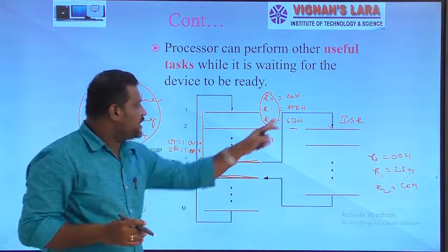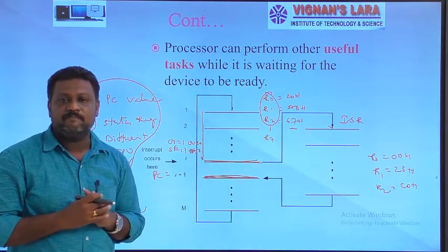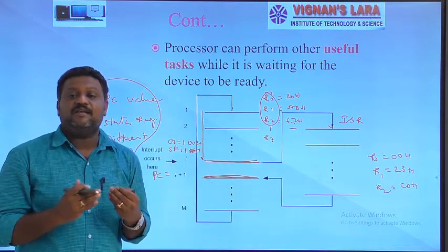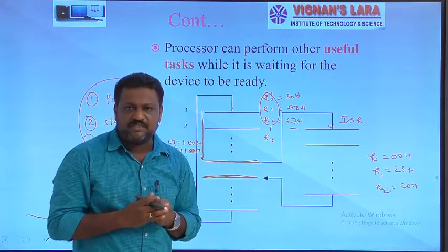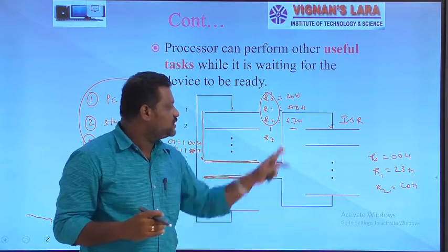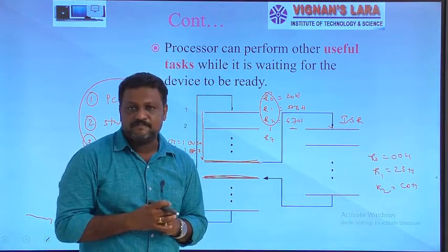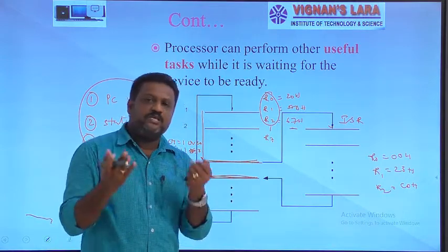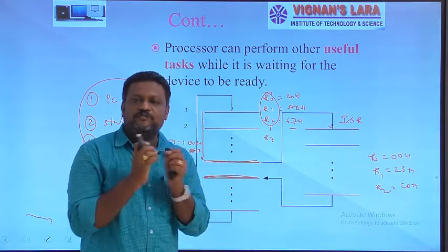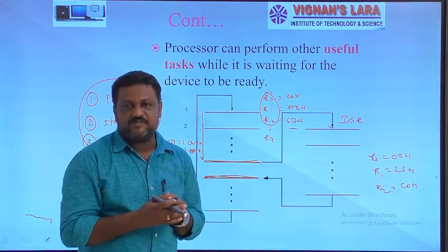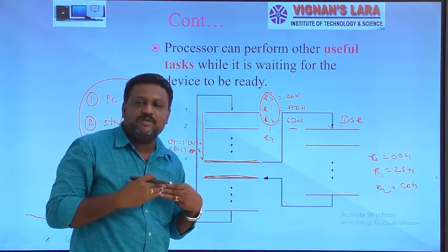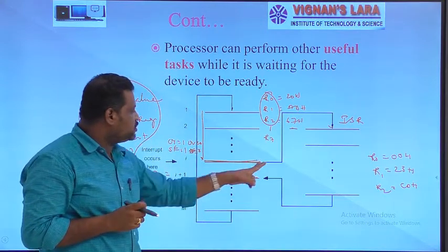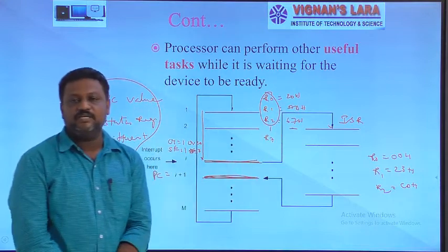We have different methods for calculation of a service routine address. So by using any one method, once we finalize the starting address of the service routine, that value is copied onto the program counter PC, and only then our execution is shifted here.